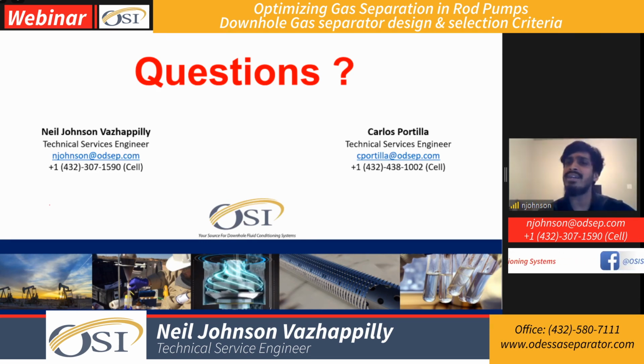Yeah, the other thing about the packer type is a very good question: since we have that much storage sump, we're going to have a bunch of stagnant fluid in that section. So the question is, in corrosive wells, can we see a lot of issues with holes in the separator? That is definitely possible if the right chemical recommendation is not made, because, like I mentioned, that storage sump helps in not running the pump dry.